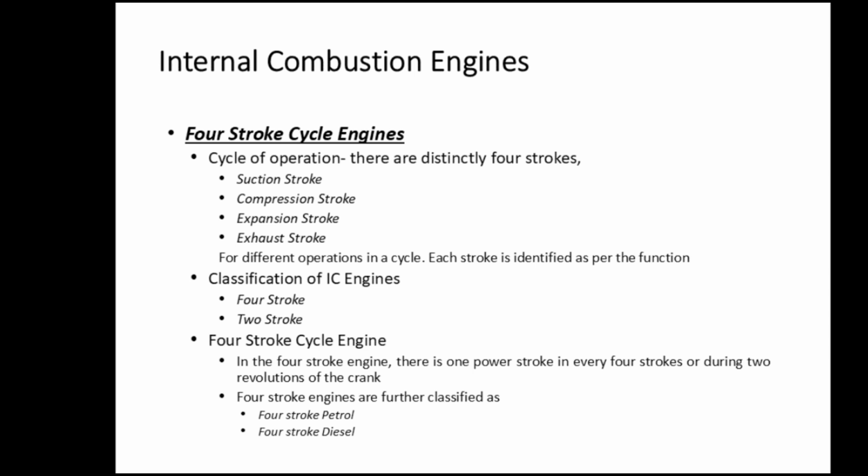Classification of internal combustion engines: 4-stroke and 2-stroke. In the 4-stroke cycle engine, there is one power stroke in every 4 strokes, or during 2 revolutions of the crank. 4-stroke engines are further classified as 4-stroke petrol and 4-stroke diesel.